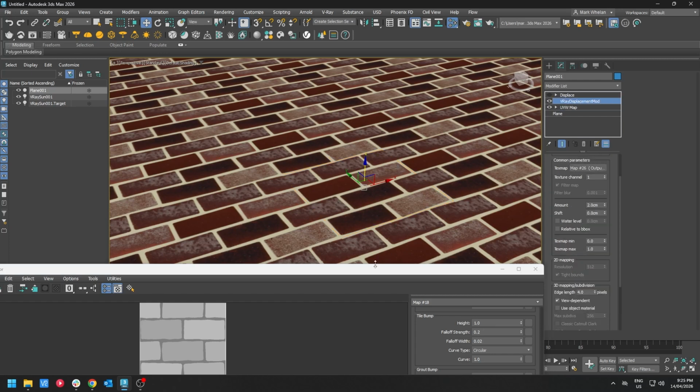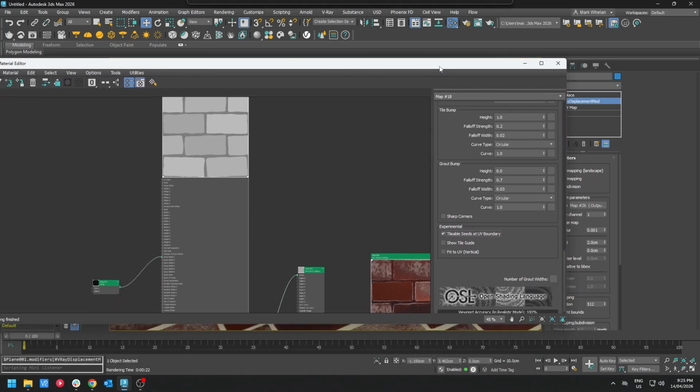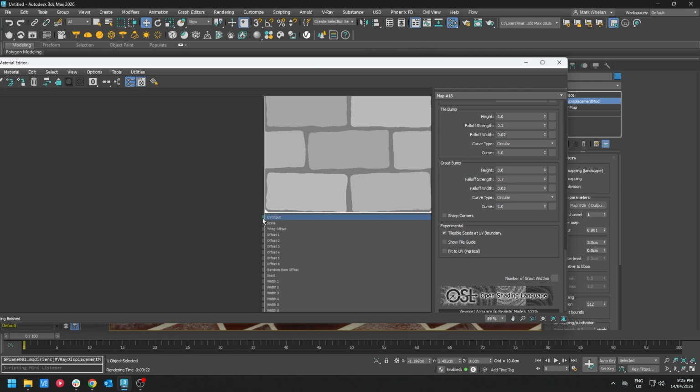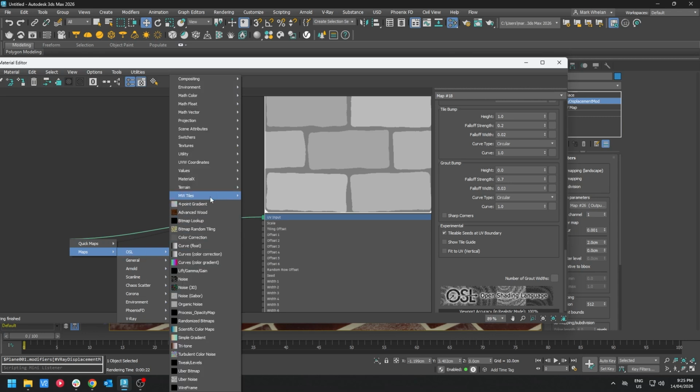And we can change our texture map, well, a displacement type to 2D now, and it will work much faster. One thing I'll change, just in case, is for the UV input, is to clamp the UV coordinates.